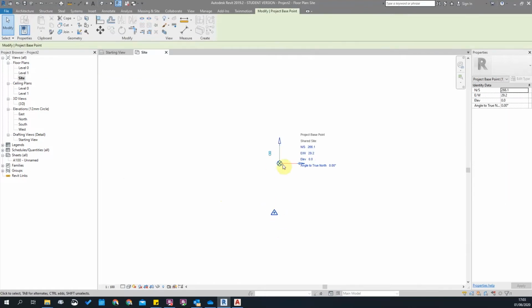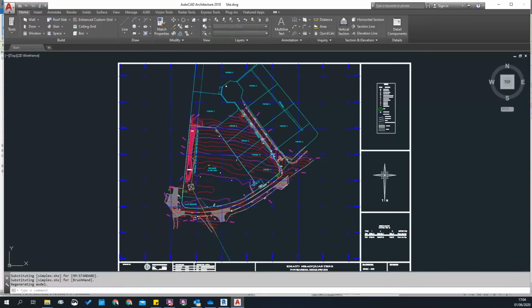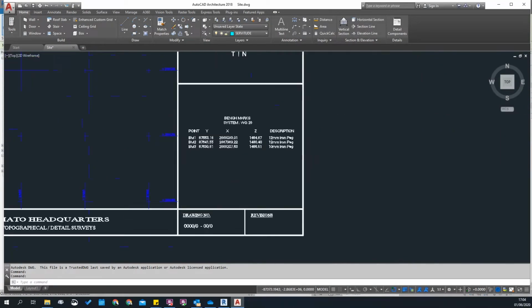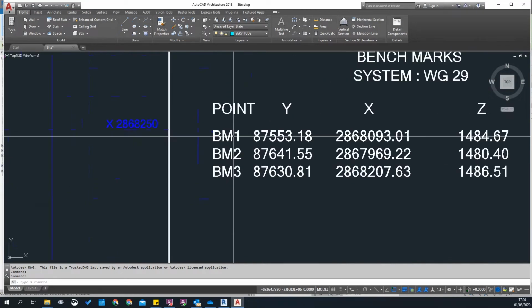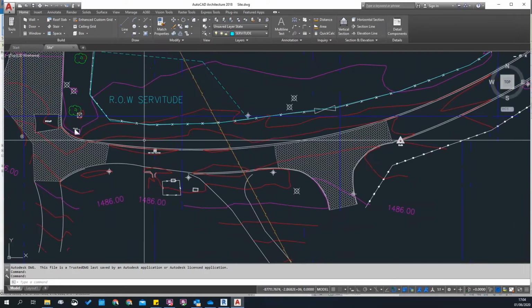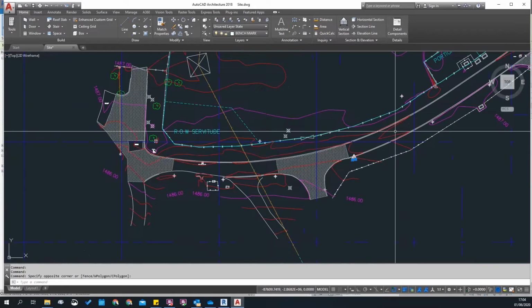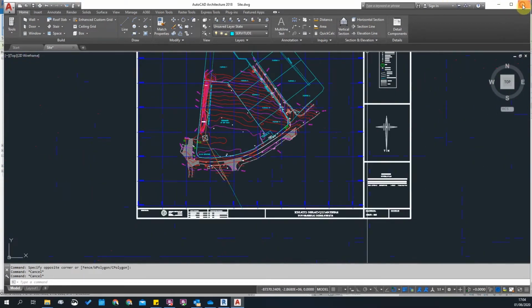The survey point is in essence where this building is set out in relation to the survey point. You could see it as an AutoCAD file; you could see that as one of your benchmark coordinates. But you must take note of this so that you can share it with your other consultants. You can see they label those pegs BM. Here they are. This is survey point 1. It's where they surveyed from. So close that for now.